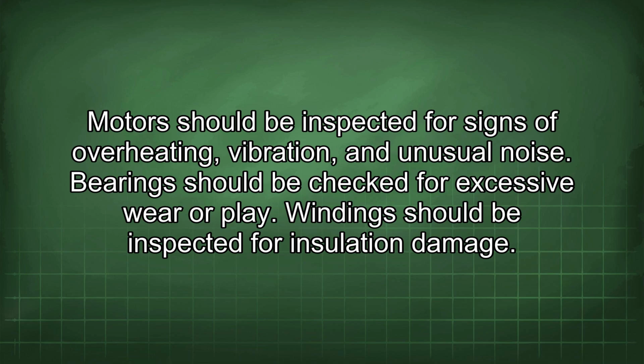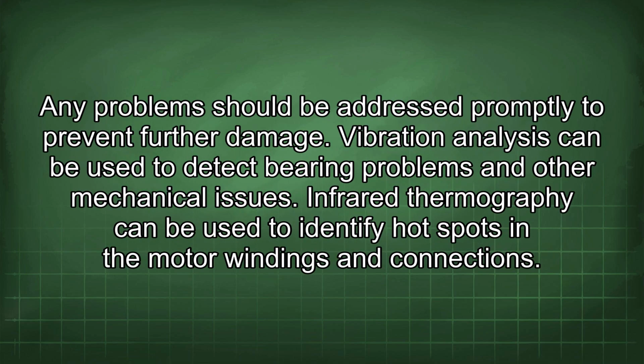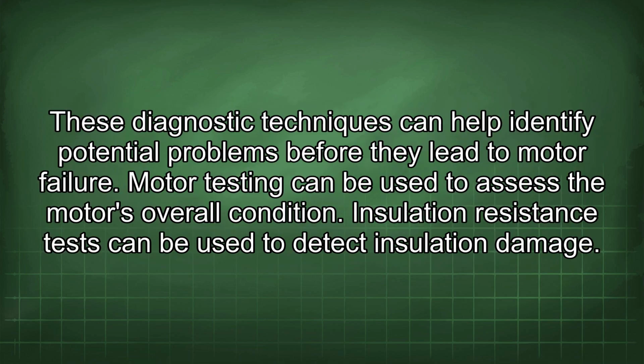Bearings should be checked for excessive wear or play. Windings should be inspected for insulation damage. Any problems should be addressed promptly to prevent further damage. Vibration analysis can be used to detect bearing problems and other mechanical issues. Infrared thermography can be used to identify hot spots in the motor windings and connections. These diagnostic techniques can help identify potential problems before they lead to motor failure.